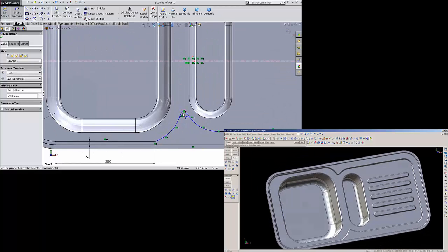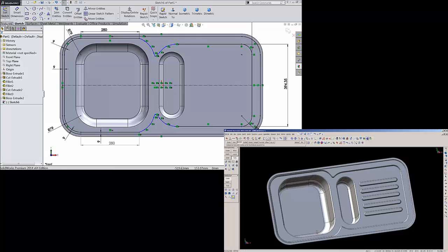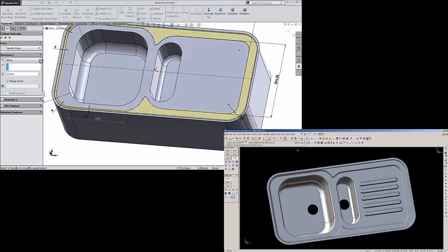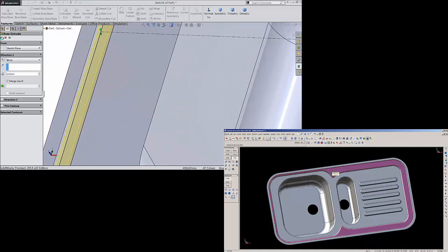Now this ellipse, this spline, you can define it also, but I don't want to waste that much time, so let's go and select here extruded boss. See this portion extruded, and extrude only up to 5 mm, a small thickness, you can see here. Okay.